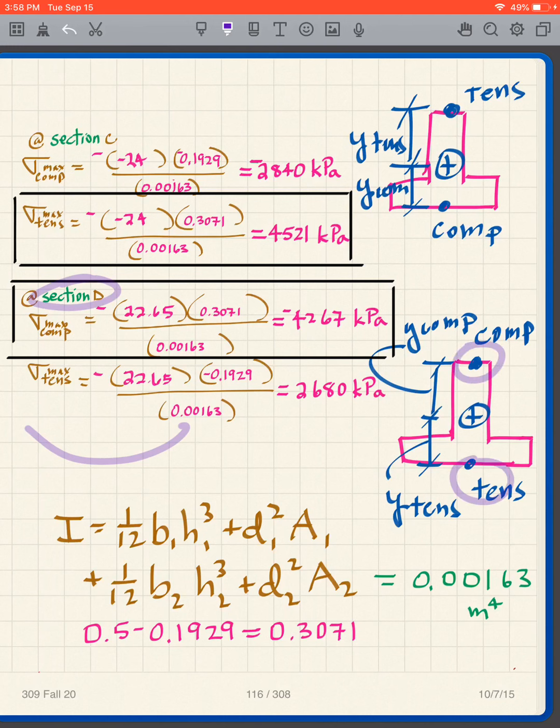So you need to know what a negative moment diagram does and what a positive moment diagram does in terms of the shape of the beam. And you need to know this is a positive bending moment, happy face, whatever you want. Sad face is negative moment. So positive is happy, negative is sad. That's one way to remember it.